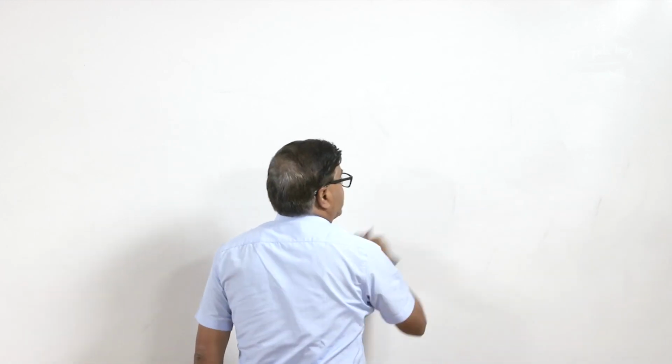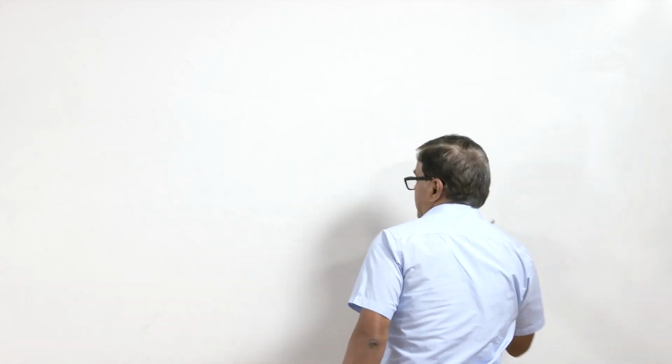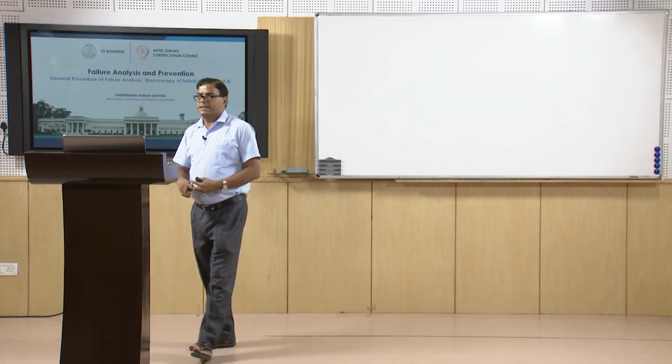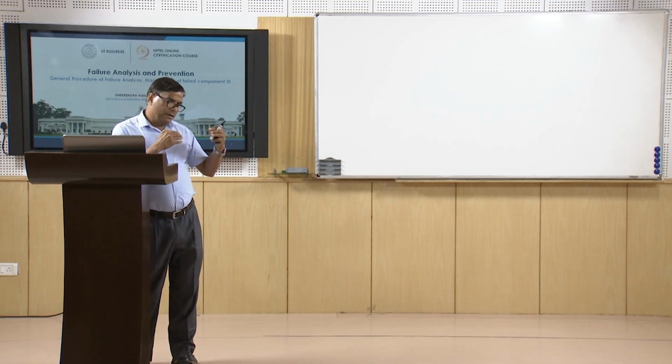So, as per the case, there may be a lot of circumferential cracks, or the reduction in cross sectional area may be above 98 or 99% if the material is resisting the grain boundary sliding. These are the macrographs showing a lot of cracks, and as I have said, due to the relative movement from grain boundary sliding, a lot of voids are formed at the grain boundaries, and that is why this kind of fracture also becomes an intergranular fracture. I will talk about intergranular and transgranular fracture subsequently when we talk about the microscopy of the fracture surfaces.